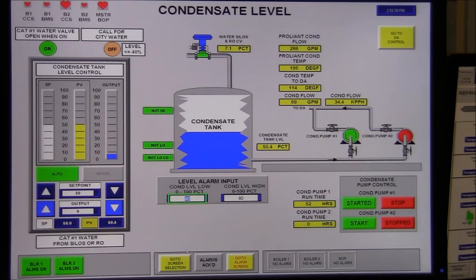The screens available out there are identical to these screens. The difference is alarm entries out on those screens. If you touch the alarm field, a small keypad will come up and the operator can enter his alarm values on the keypad, click the download button, and it will write it into the program. In the control room, any operator entries have to be through the keypad.